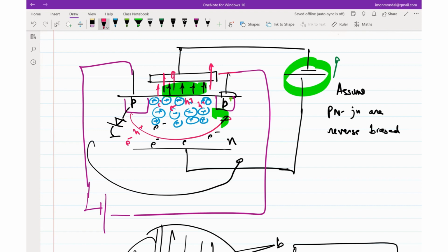So you are going to have electron and hole pairs which are going to get generated, but the electrons are going to get pushed out and the holes will remain. But the good thing is that these holes are all mobile. They are positive mobile charges, right? So after you apply some critical electric field, what is the critical field is a different thing, but looks like there is a way of applying some critical electric field where I can fill that part just underneath with positive mobile charges.